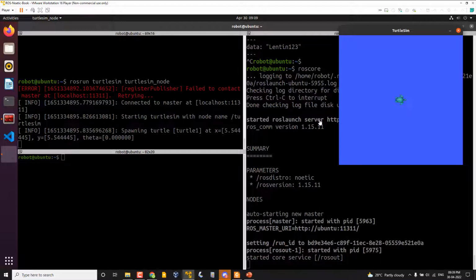In order to move a mobile robot, you have to give two kinds of velocity: linear and angular velocity. The linear velocity drives the robot forward, and the angular velocity gives the angular displacement, or the twist, the deviation, while linear only goes forward. So the combination of linear and angular will move the robot to any place.